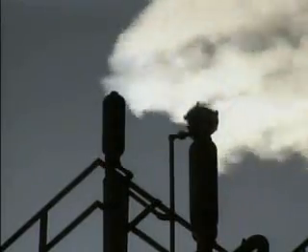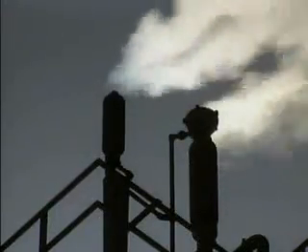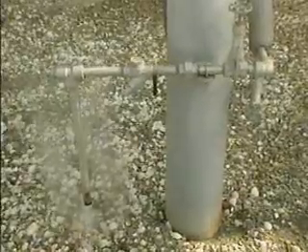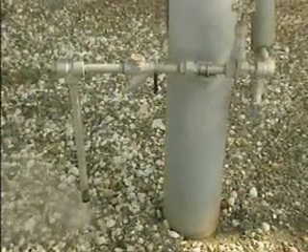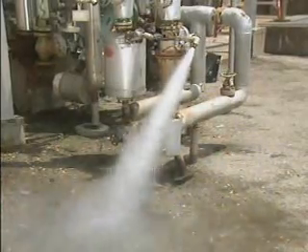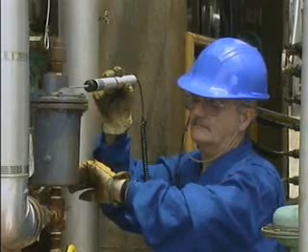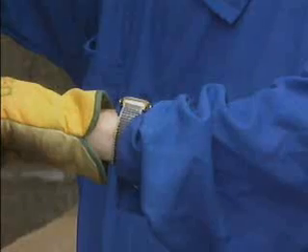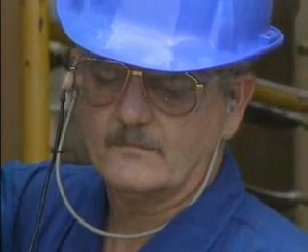Live steam is produced in the steam system's boiler. It's usually discharged with more force than flash steam is, and it has no center core of hot condensate. If it's working properly, a steam trap should be discharging hot condensate with some flash steam. But if it's discharging live steam, the trap isn't working properly, and it must be repaired or replaced. If the discharge is intermittent, the cycle rate should be timed, and the time should be compared with the cycle time that your facility or the manufacturer lists as normal for that particular trap.